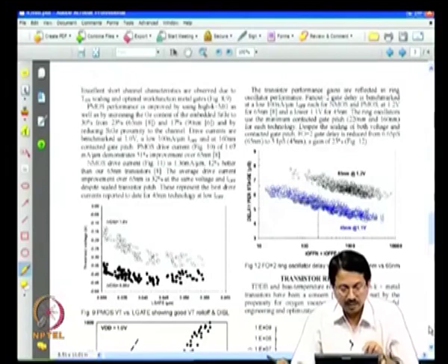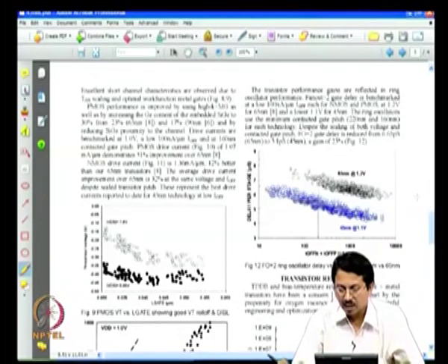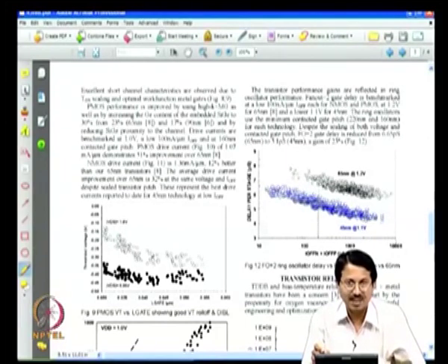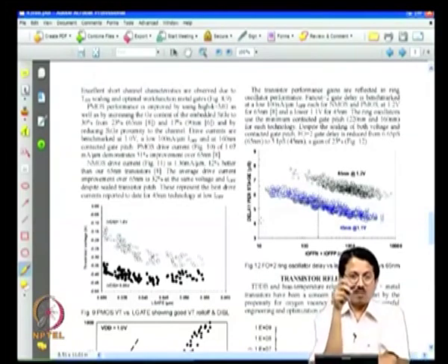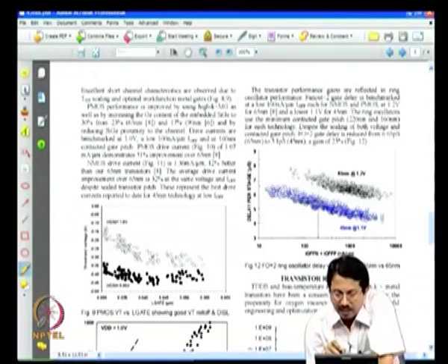That is for N channel, and this is for P channel transistors. Okay. Typical off current versus on current plots, this looks similar, everything looks similar. And now typical delay versus off current, remember this is how it looks. When you have very large off current, it means the smallest length transistor has the highest leakage current, and hence because you have built the inverter using the smallest length transistor, you have the best delay that you can get, and the delays are now of the order of very low delays of 5 picoseconds or even less than 5 picoseconds.